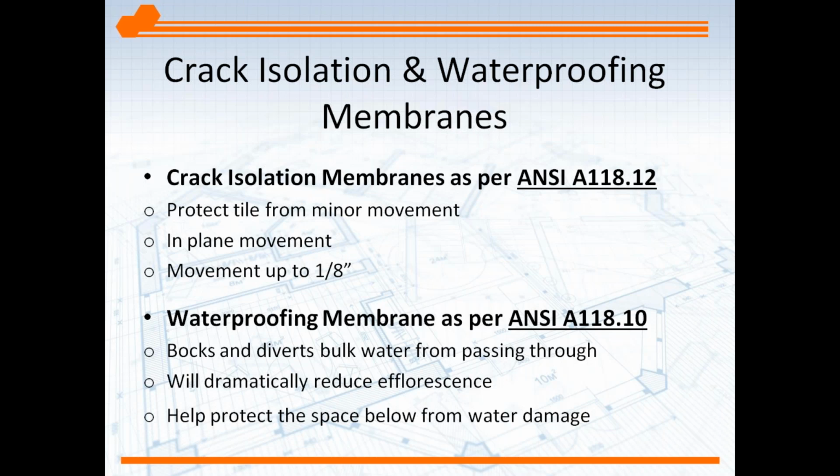So what does a crack isolation membrane do? It's going to protect the tile from the minor movement, and it's the in-plane movement. We consider in-plane movement, we'll say side to side. It's not going to protect the flooring above if the concrete movement is not side to side. Let's say that it's raising up on one side of a crack, or dropping on one side of the crack, which is the same effect. That's up and down. That's not in-plane movement, and these membranes are not designed to handle that type of movement. They're designed to handle the in-plane. And when we say minor, the standard is 1/8 inch of movement. So the ANSI standard for A118.12 is to be able to handle 1/8 inch of movement of the substrate.